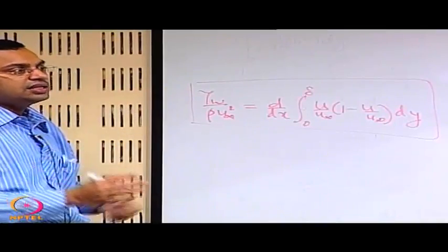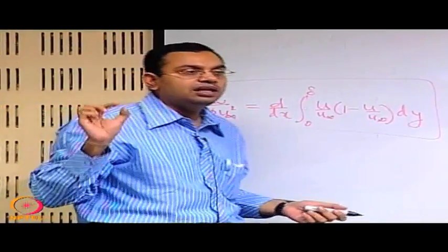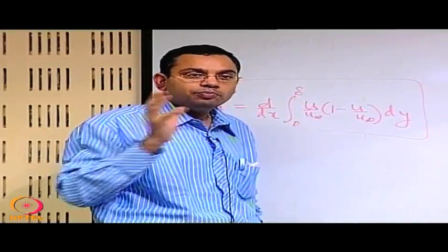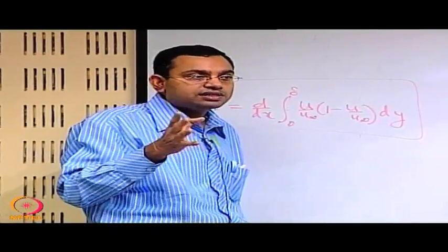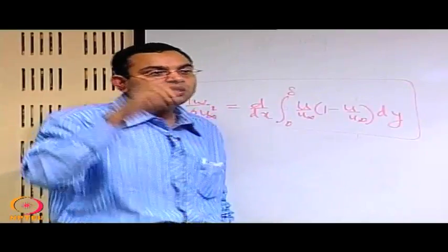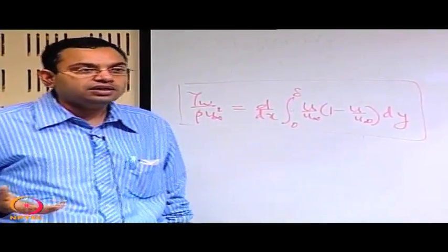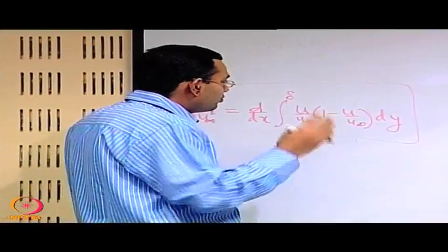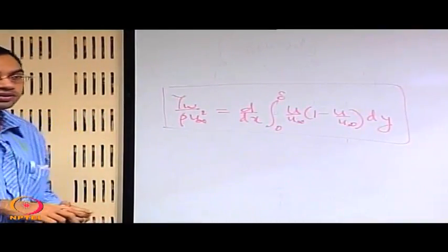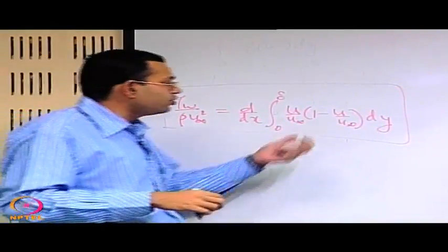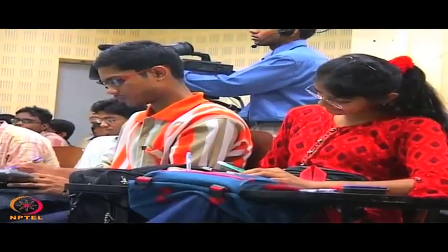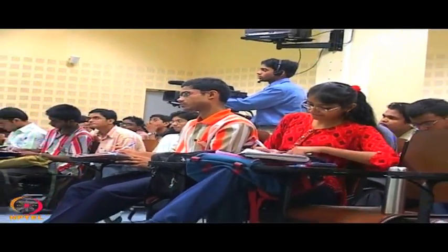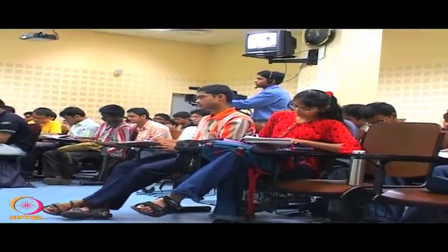And this expectation is from the fact that after all the boundary layer is very thin, so error in the velocity profile may be important when you consider the velocity profile as such, but in the integral sense the integral of the velocity profile might not be that erroneous. So that is one of the expectations. Whether that expectation is justified or not, the best way to look into it is by some example. So let us say that we want to have a polynomial approximation of the velocity profile.